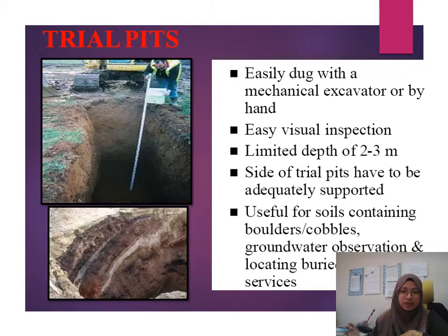Because it will be more dangerous, as it has a tendency to collapse. So the depth is only up to 2 to 3 meters. The sides of a trial pit have to be adequately supported, depending on the type of soil. If the soil is very stiff, it can remain unsupported, so it's okay.